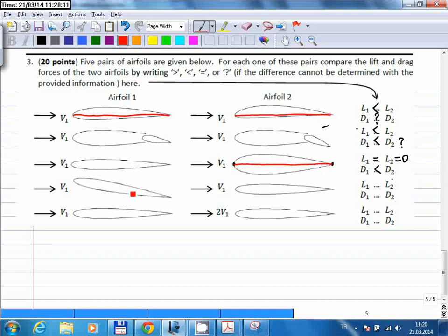Okay, so in the fourth case, we have the same airfoil, and the first one is at a positive angle of attack, while the second one is at 0 angle of attack. And obviously the first airfoil should create more lift force. And in fact, the lift force for the second one should be 0. And in terms of drag forces, the drag force for the first one should be greater than the second one because it's...